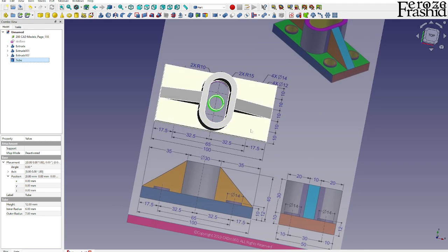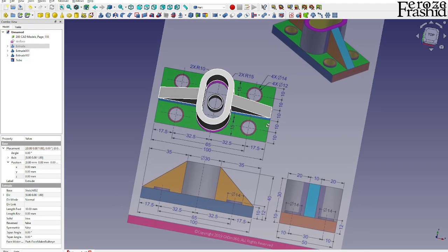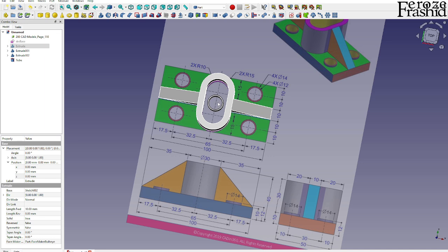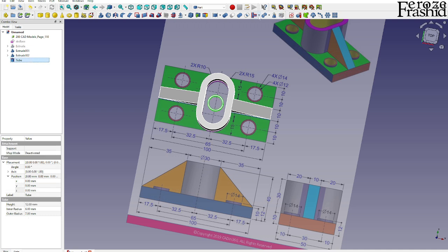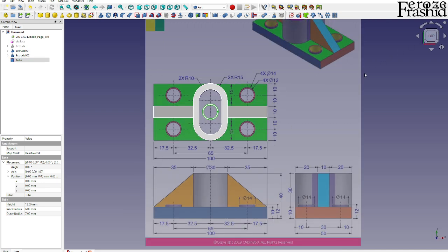We want to move it to the position right here, so it would be 15 millimeter downward. So from here to here it is 15. Let's update the location: on the y side, it would be minus 15, and on the x side, it would be minus 32.5. So that is one placed in location.